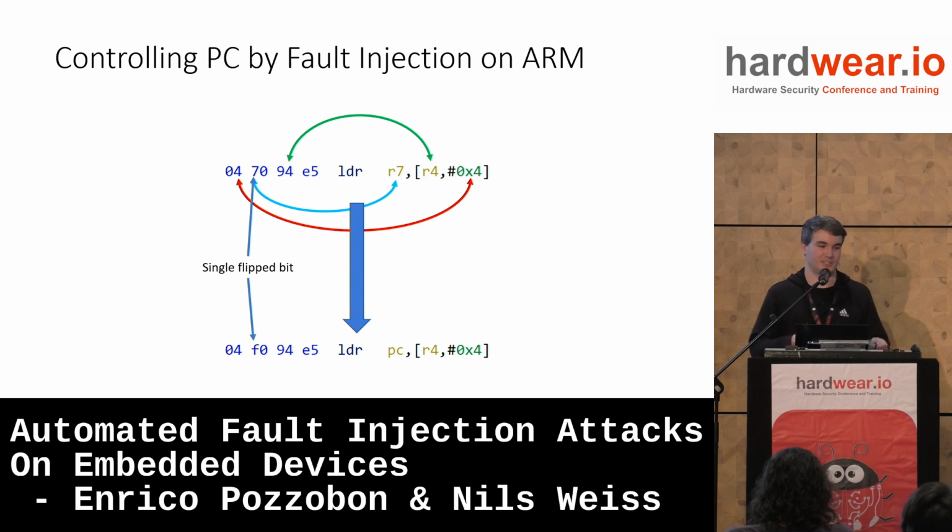At the beginning, we didn't have the firmware of the bootloader, so we didn't know which instructions we were attacking. We just randomized the time. Also, even if we had a specific instruction to attack, the timing of the execution of this firmware was so undeterministic that it was not possible for us, even later, to target a specific instruction, at least with the limited trigger capabilities that we had.